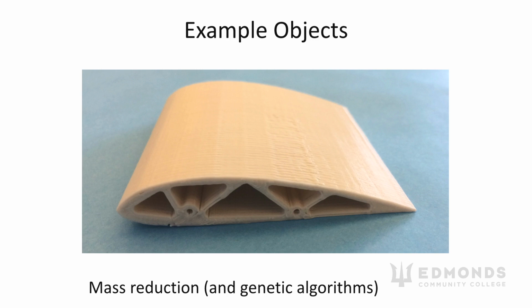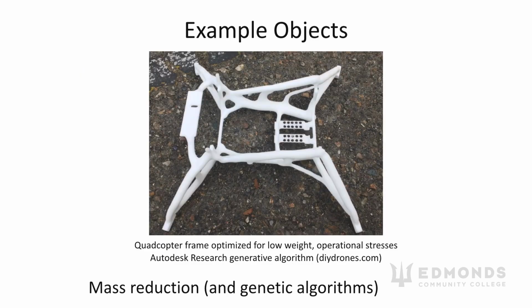However, if you look up genetic algorithms or computer AI, iterative design, topology optimization, then you may find shapes like this that are even more complex and look a lot more organic as a result. Additive manufacturing is pretty much required in order to produce those parts because otherwise we can't leave that hollow space where we want with traditional manufacturing techniques.